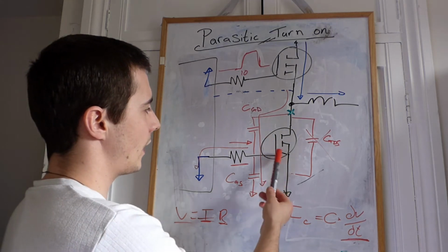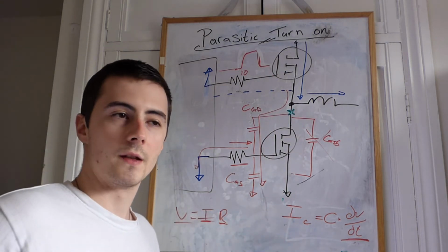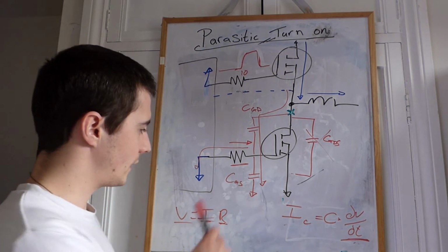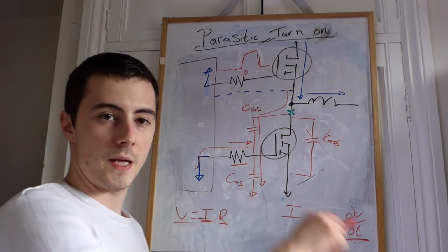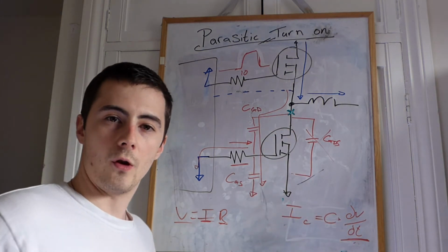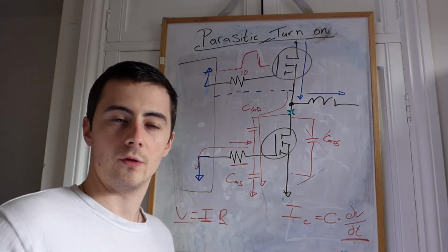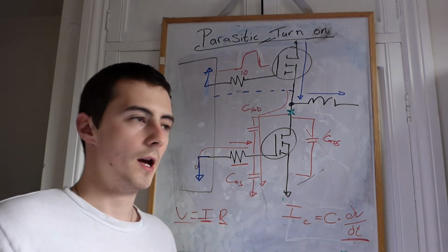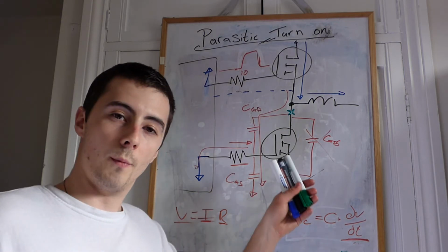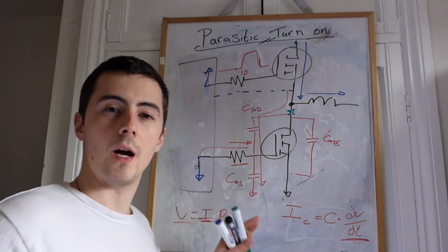That's going to be putting a large amount of current through your FETs, and it'll be for a short period of time because these little peaks that we're going to be observing don't happen for a long time. But if you're switching several 100,000 times a second, then eventually those are going to warm up, and they're going to fail prematurely. And this is where this comes from.